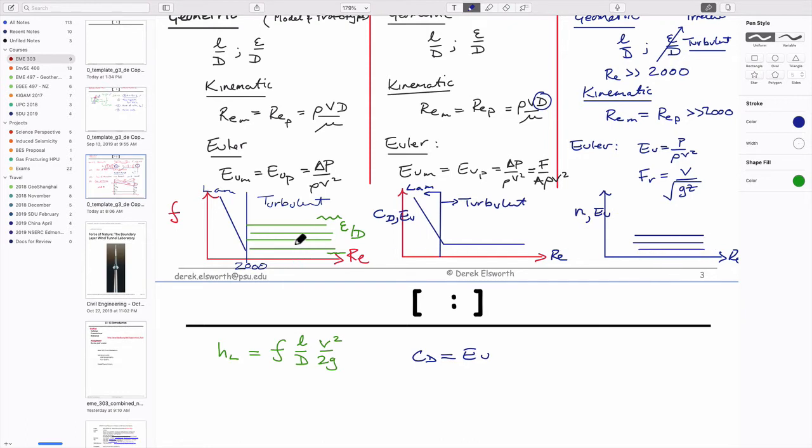For channels, these would also be relative to their roughness. So one might be a glass channel, one might be a concrete channel, one might be an earth channel, with different roughnesses attached to them. There would be a laminar part in this regime, but we don't care about this because almost all flows in open channels, because the Reynolds number is big, are almost all turbulent.